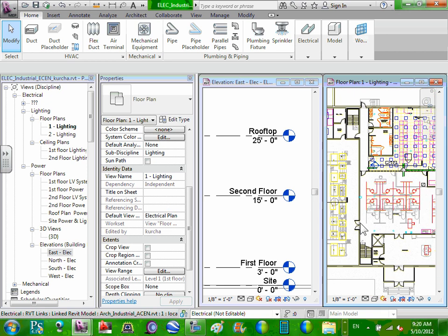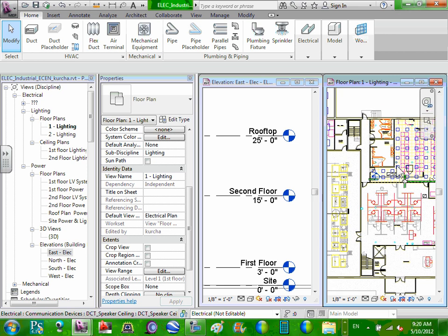That kind of comes, if you're using a DWG as the background, do you actually have the walls and doors modeled in Revit? Yeah. Okay. Because sometimes on projects, we can get a background that's just a DWG, and we're just placing our 3D elements around on that DWG. And basically, you put it into a 3D and you just see electrical things floating around because they don't have any walls. But if you have a model like we have here, that's where we are cutting all your model's links. So at 4 feet, we take a big slice, and whatever that top shell looks like is what you're going to be seeing.